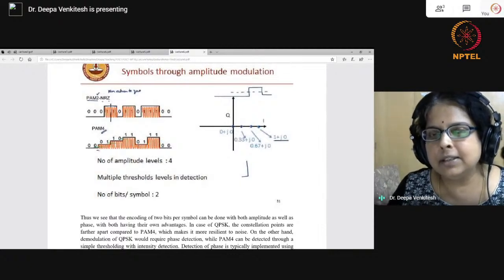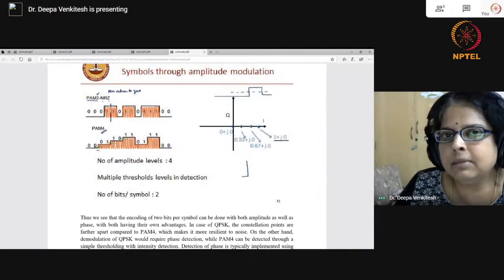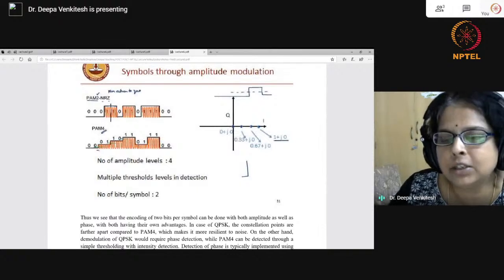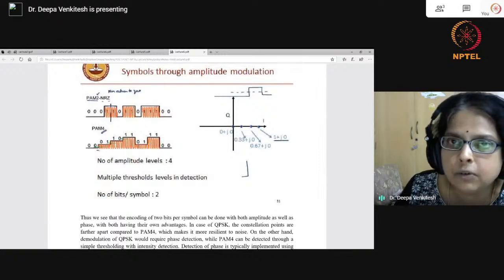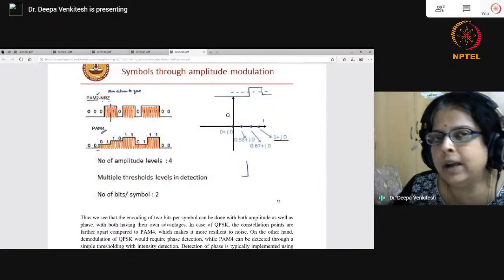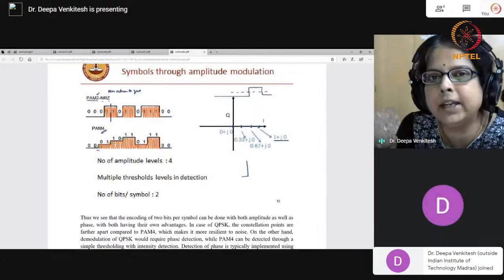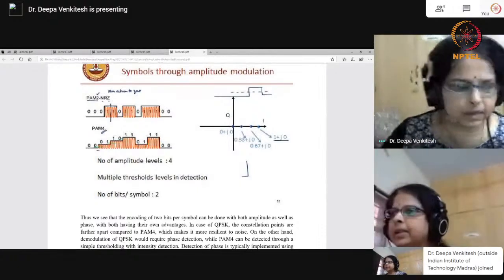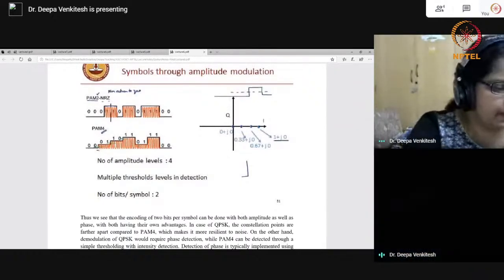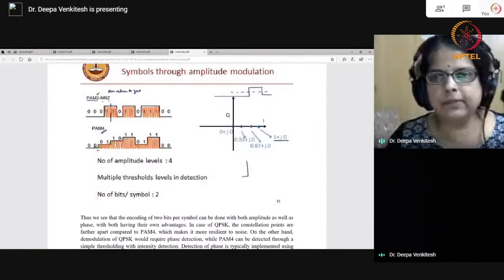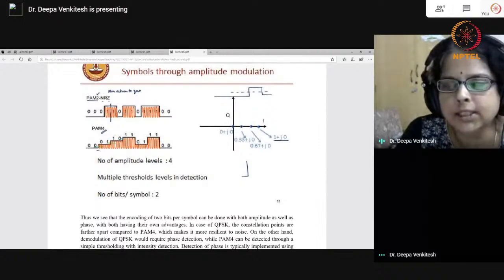Even if there is loss at 1300, the distance is not much, so the net loss is not much, whereas the dispersion is 0 for 1300, right? So I don't have to do any kind of dispersion compensation, especially when I go for very high data rate systems. So I would prefer 1300 nanometer for such a short distance link.